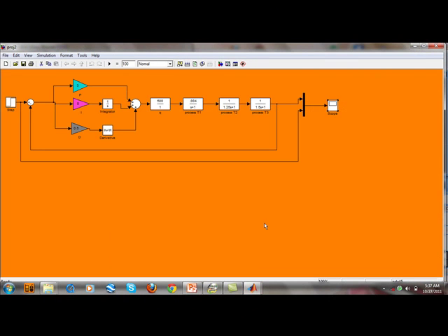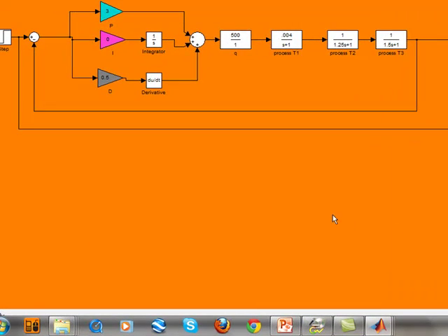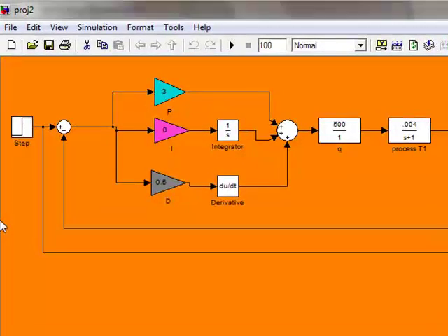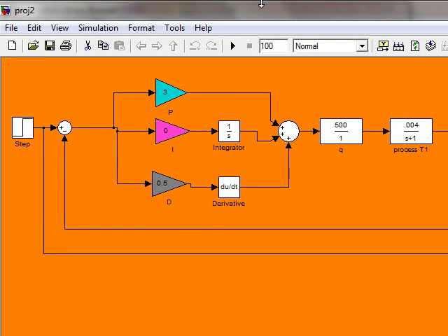As you can see, the source is a step input. It is connected then into the simplified PID block. It is preferred to use the simplified form to avoid fluctuations in the graph that depend on the filters set when using the actual PID block. The blue one is for the proportional with 3 as the gain, 0 for integral since it is a PD controller, and the time derivative is 0.5 for the derivative part.